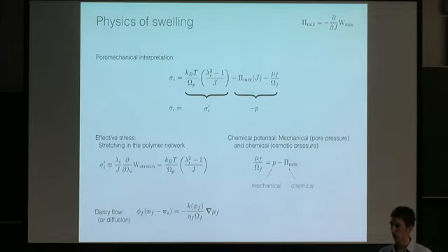Ish. Majid: One thing that's a little confusing is that when you write Darcy's law, the velocity is on the left. Yes, those are macroscale quantities. Yes, averaged over a large amount of water. Then on the right you talk about molecular properties? Well, they are molecular, but they're at the continuum level. So it's the chemical potential at a point, and your point isn't really an REV. So we're not modeling at the molecular level. It's still a continuum.